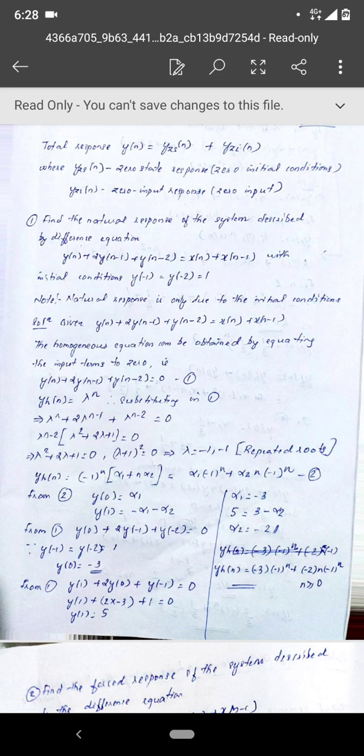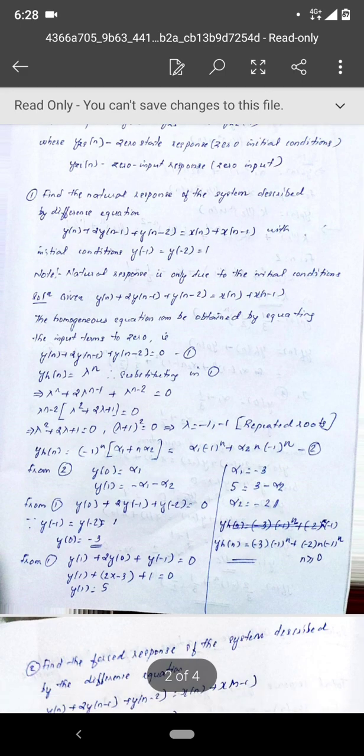That is, if we have the voltage source alone, what is the current through that resistance? At that time we have to kill the current source. Then we take the current source alone. At that time we'll be killing the voltage source, and we'll be finding the current through that resistor alone. And then we add up those two currents, and we'll get the final total current passing through that resistor. That is one at a time. That is what is called the superposition principle. The same thing we'll be applying here also.